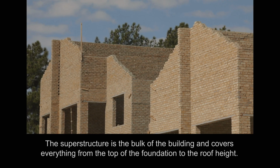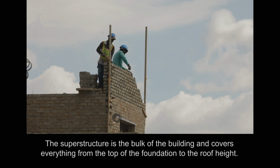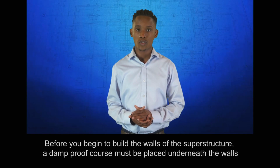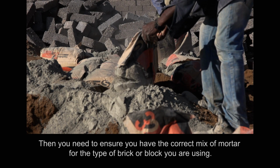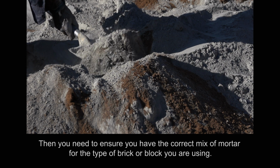The superstructure is the bulk of the building and covers everything from the top of the foundation to the roof height. Before you begin to build the walls of the superstructure, a damp-proof course must be placed underneath the walls as per this image. Then you need to ensure you have the correct mix of mortar for the type of brick or block you are using.